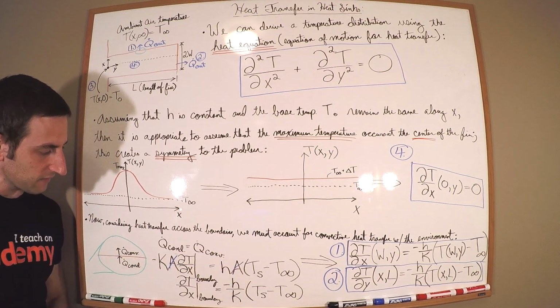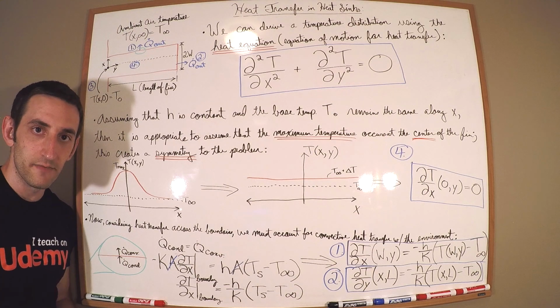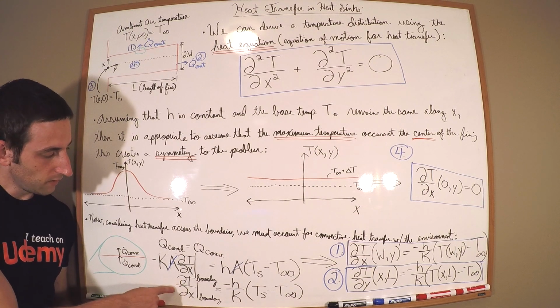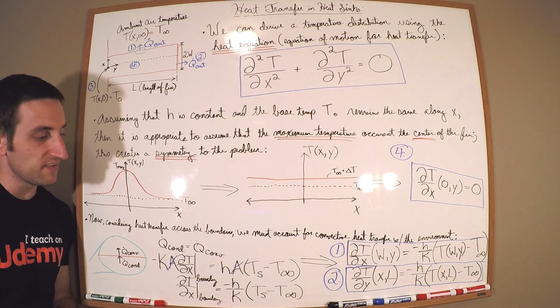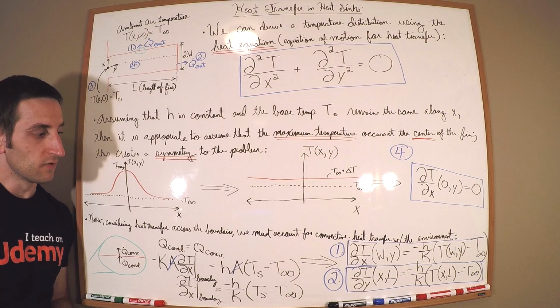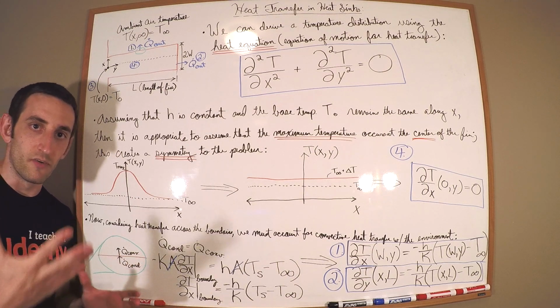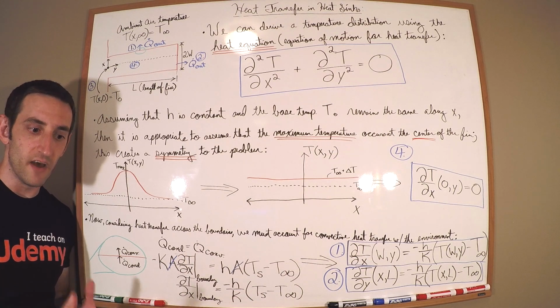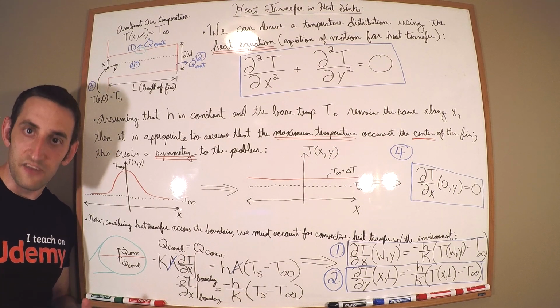We can cancel that guy out. Divide the negative k over here. The boundary condition we get, the derivative, is going to be equal to negative h over k times the quantity Ts minus T infinity. Okay? So we're trying to eliminate this discontinuity at the boundary, so our temperature distribution is nice, it behaves in an orderly fashion, and conforms to how nature does things.